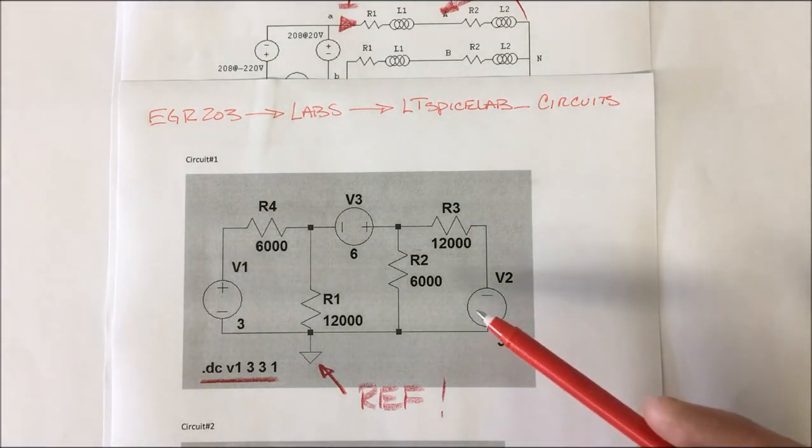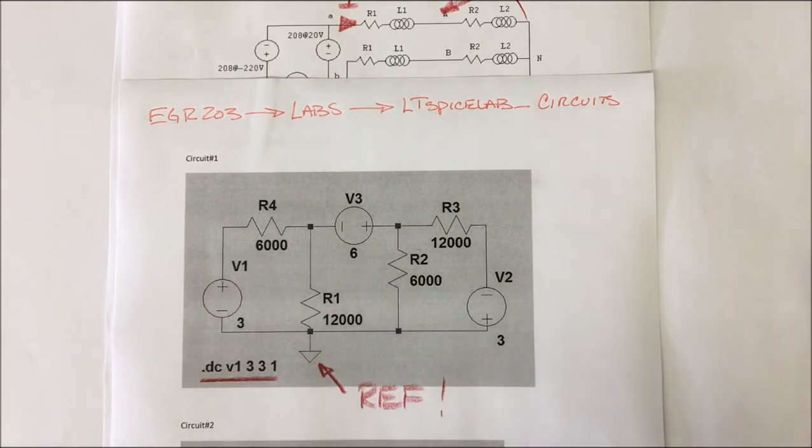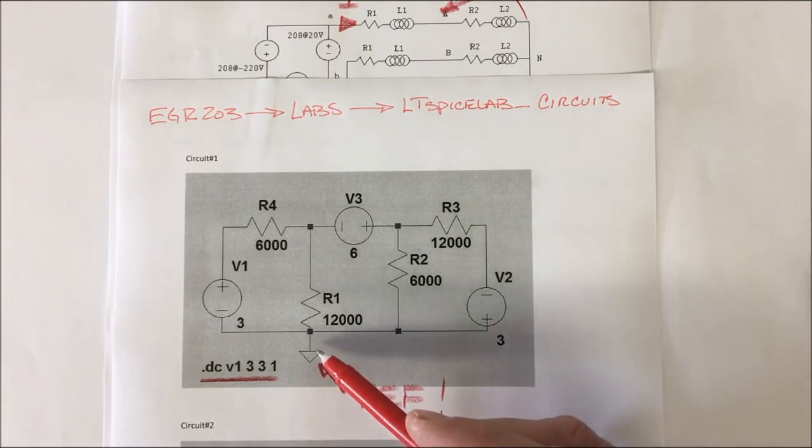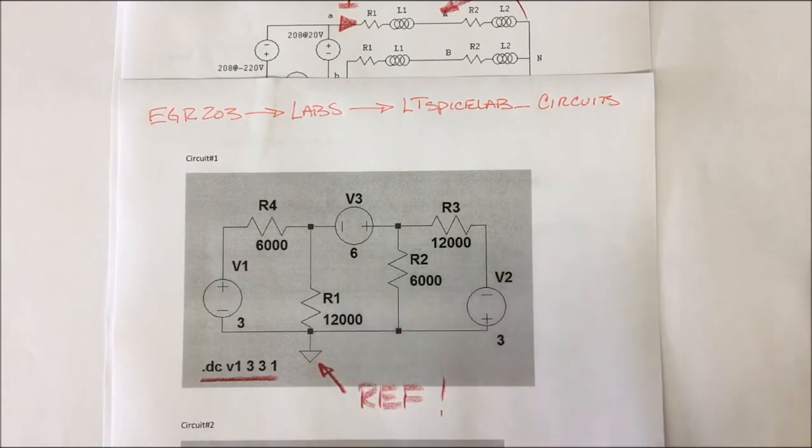So a couple of things as we go through these. This is a dot command, so if you have a dot and some commands, that's the way you can get it to do something. There are other ways of doing it. This is a little bit old-fashioned, but that's what that is. One thing that every circuit needs is a reference to 0. So this is going to be a 0 node down here, and you have to have that ground, that reference.